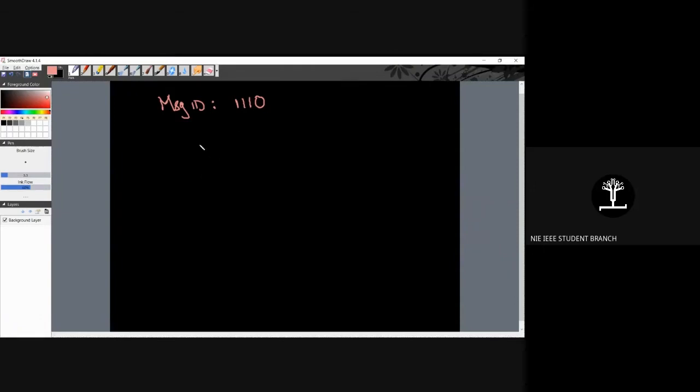And please note, CAN protocol is actually very complex and way more difficult than what we are doing here today, because message IDs of different units will be of arbitrary, different sizes, so it is difficult to manage. Here we are taking a bus and just tracking one device specifically which is connected to the bus. So how do we do it? This is perfectly an example for a sequence detector. I want to detect the sequence 1110, and only then I'll know that that device is transmitting data or receiving data, or using the bus basically.